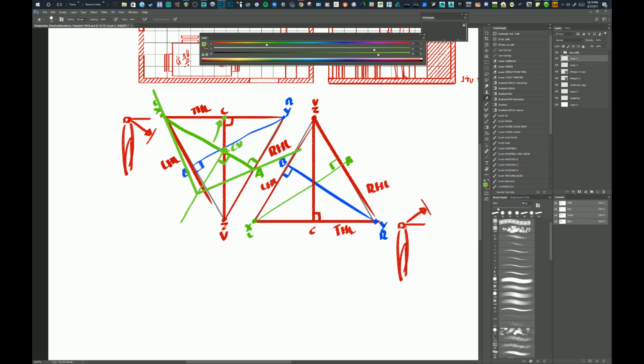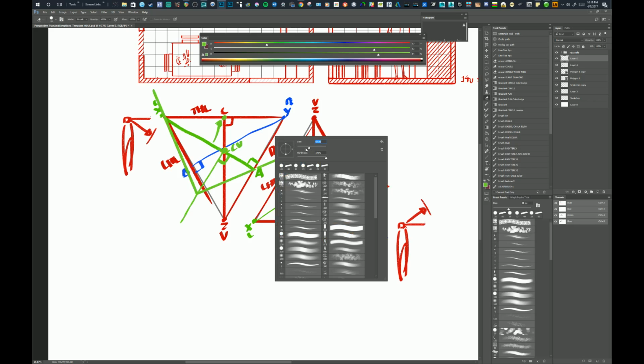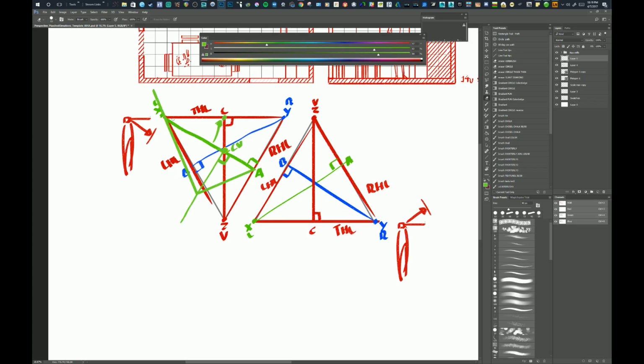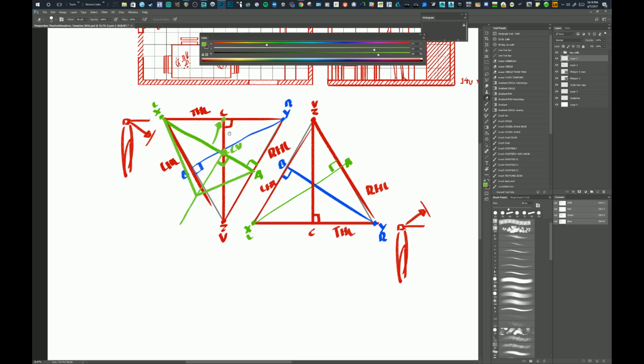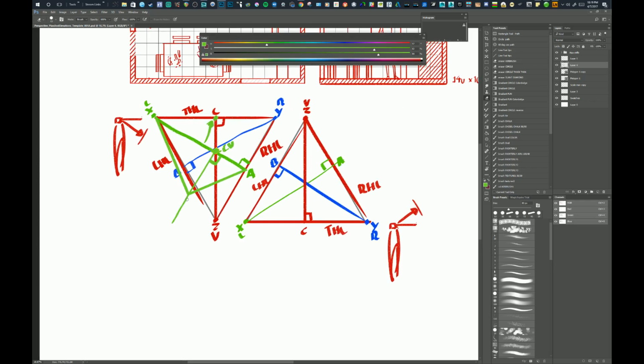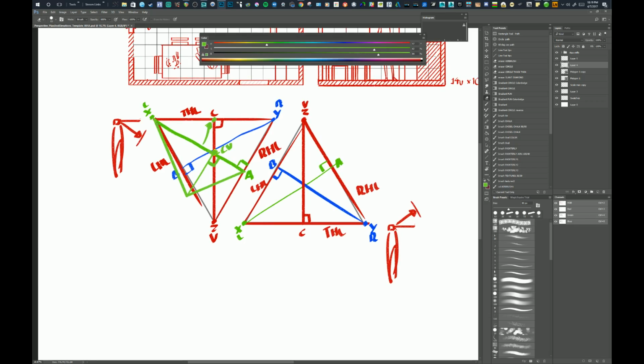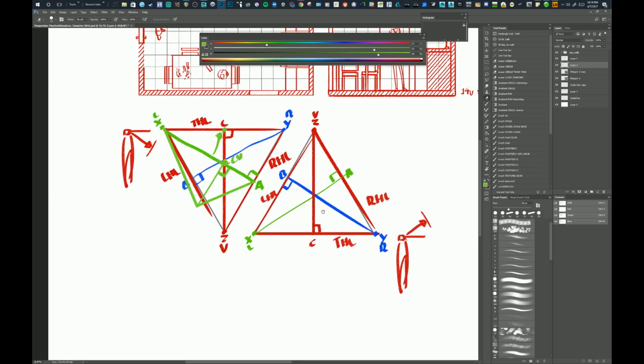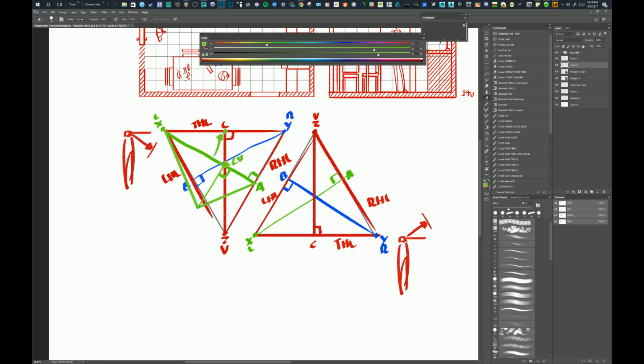Now I would do this for every one of my reference lines, or what I'm going to do here, since I already know this and I've already found my half kite. I like to call it a half kite because I see patterns much easier than I see technical math stuff. So if you notice, for this reference line, I have this symbolic half of a kite, and notice how it's also facing down. So the X and the Y will have a half kite that's facing down when we're looking down. For the X and the Y, when looking up, the half kite will be looking up for each of these two reference lines.